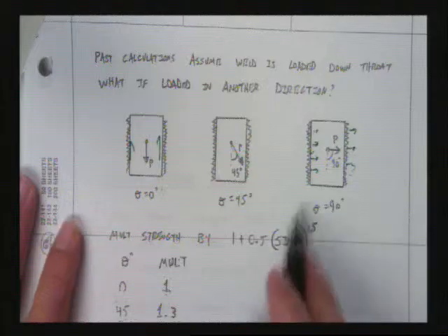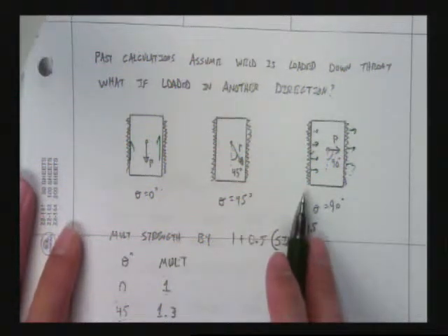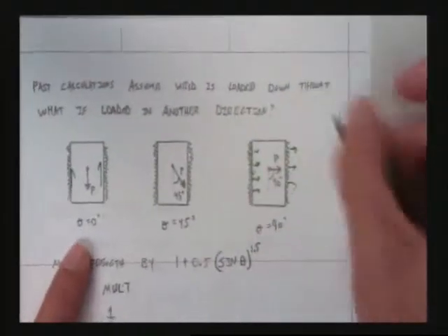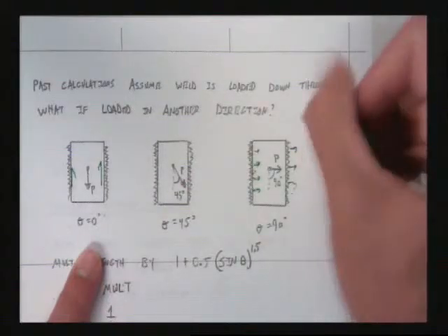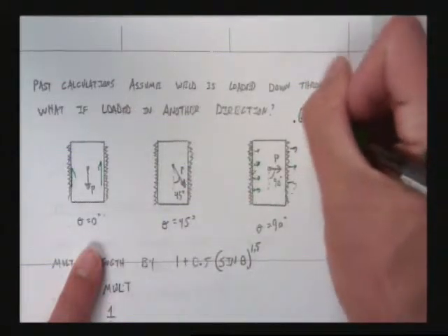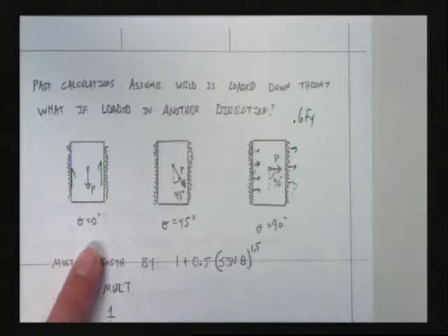And they find that actually welds in tension are much, much stronger than welds in shear. And it doesn't have to do with anything except, if you recall, it's very common to look at the shear capacity of something. If I want to know the shear capacity, it's 0.6 times Fy, or 0.6 times Fu. It's very, very common to use that.